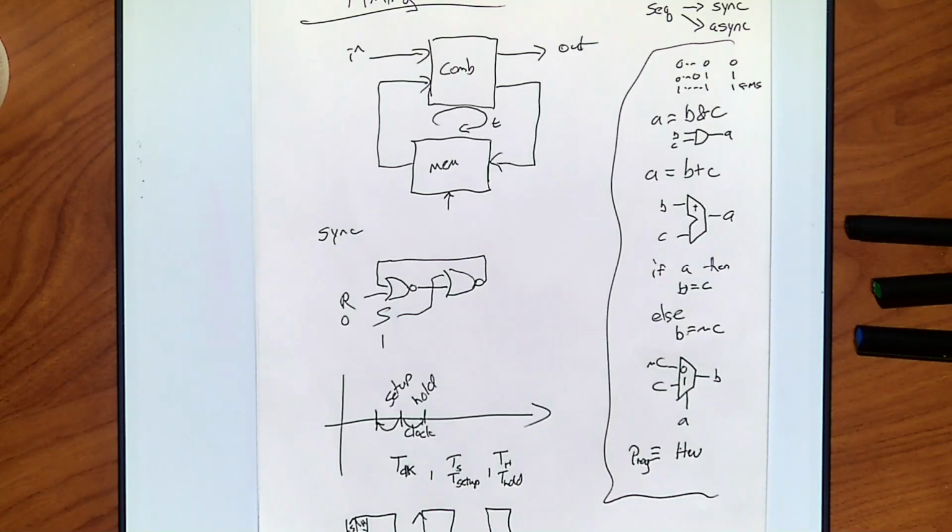Okay. And this can be different for different logic families. Some logic families are only concerned with the setup time, and once it has it, hold isn't really required. So you might find T hold equals 0. Sometimes they use their stability factors, and they make T hold have some time, and T setup is really small. More often than not, T setup will be non-zero, and T hold will either be something small or zero, which is actually due to another thing we're going to see in a few seconds here.